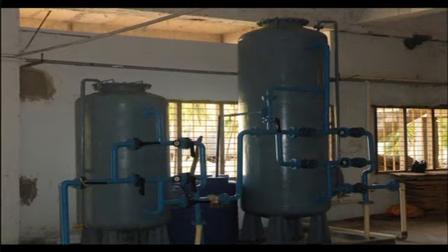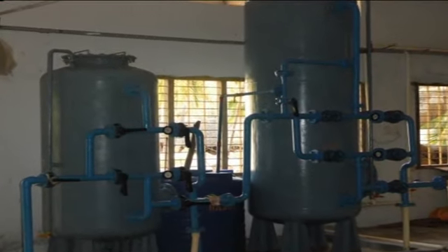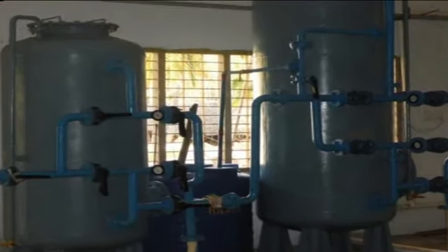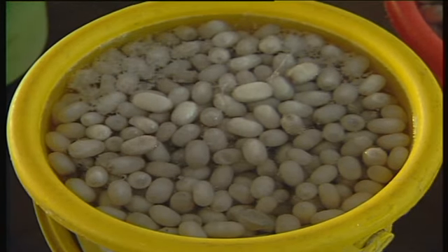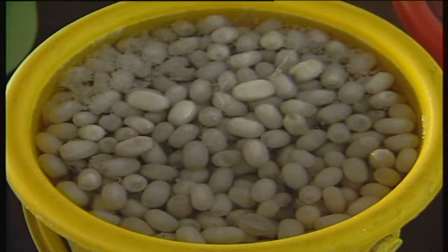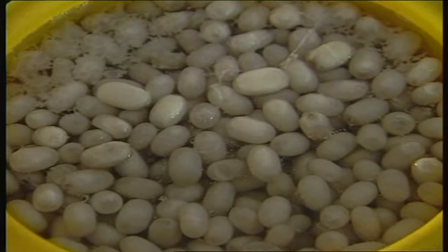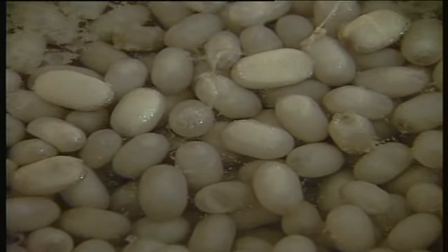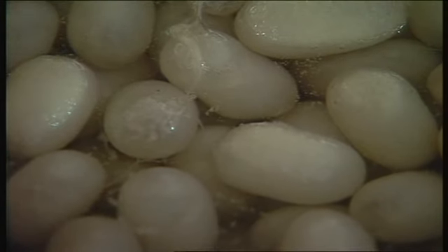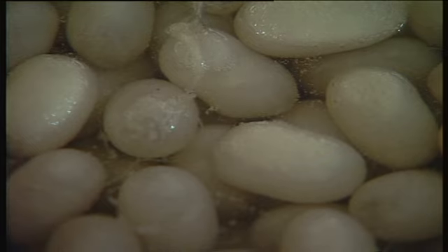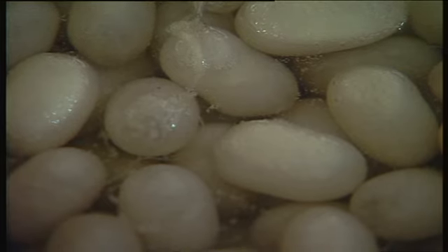High temperature zone. Cocoons which are wetted are treated at high temperatures, steaming zone, in order to permeate water into the cocoon shell. It is necessary for the temperature in the zone to be regulated depending on the cocoons. For cocoons with a thick shell layer but poor reliability, the temperature is maintained at 100 degrees centigrade, and for thin shell layer, the good reliability cocoons, the temperature is maintained at 97 to 98 degrees centigrade.